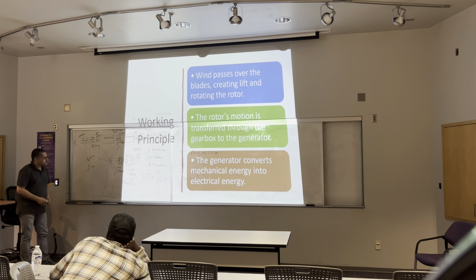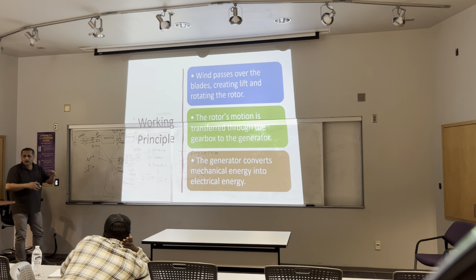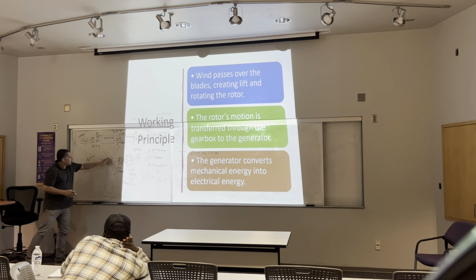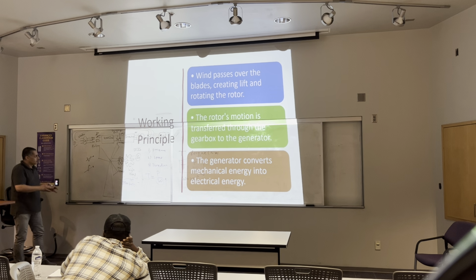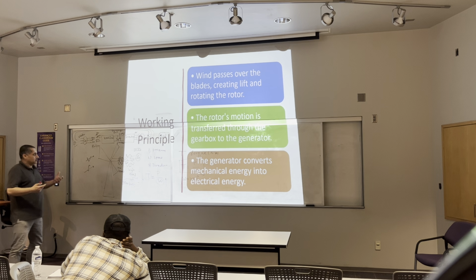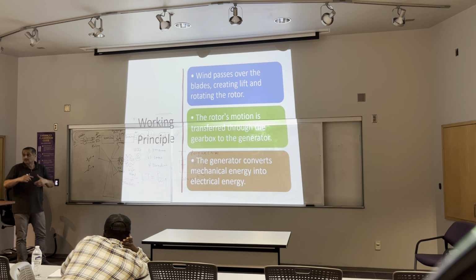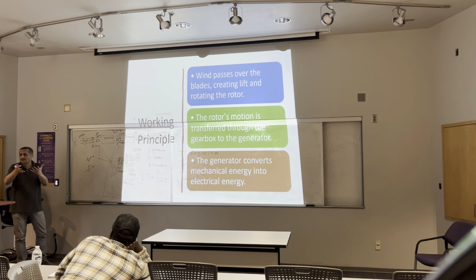Now, we convert the mechanical speed to another mechanical speed higher or lower than generated by blades or by wind. This is the first step. Now, we have a problem on the generator. The generator is variable speed, variable frequency, variable voltage. So variable speed will generate variable voltage.